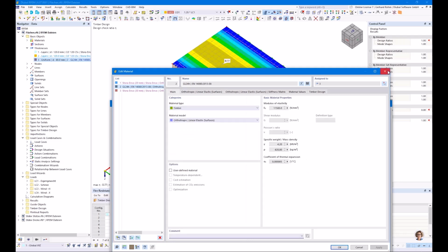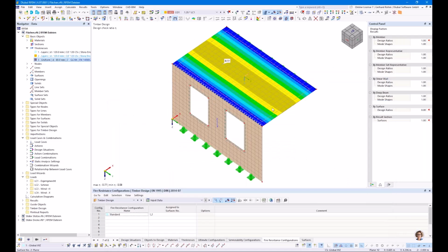And of course, there should be no moment transfer in Y direction of the surface, but since we span it directly in one direction, there is no big difference. Of course, if there is another support here, then maybe we should think about to reduce the stiffness in Y direction or add some line hinges, but for this example, it's absolutely okay.